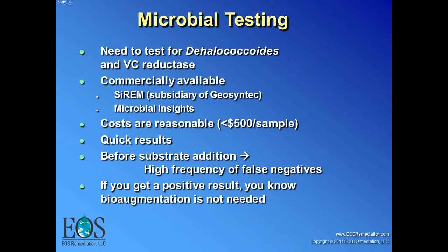How do you know if the bacteria are already there? There's a number of companies out there that will actually do testing. Two of them are SiREM, which is a subsidiary of Geosyntec, and Microbial Insights, which are probably the most common ones. You can collect a groundwater sample, send it to them, and they'll test it and tell you whether the bacteria are there or not.